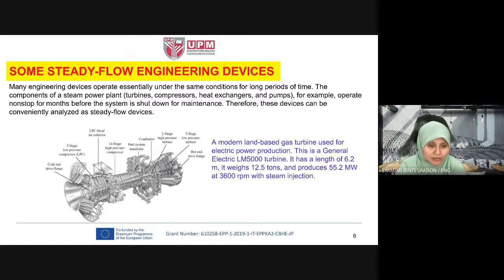So if you have a turbofan engine, there are two duct flows, duct, D-U-C-T, duct, bukan duck. Okay, there are two duct flows in a turbofan engine. One that will go through the core engine. This is the core engine. Core engine: compressor, combustion chamber, turbine. That is what we call core engine. Core, the main duct. And the other duct is for bypass fan airflow.